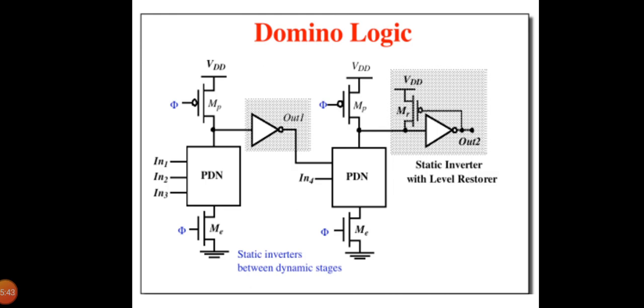A general but expensive approach to solving this problem is the use of differential logic, that is, dual rail domino. It is similar to the concept of DCVSL structure, but it uses a pre-charged load instead of a static cross-coupled PMOS load. And you can see a NAND differential logic gate. Note that all the inputs come from differential domino gates and they are low during the pre-charge phase while making a conditional 0 to 1 transition during evaluation.